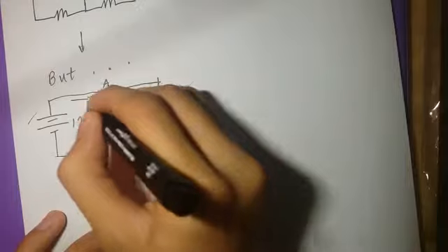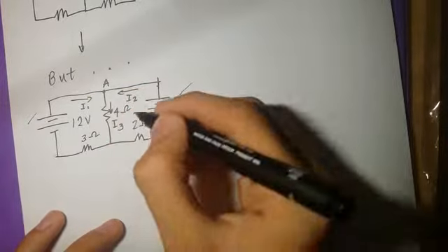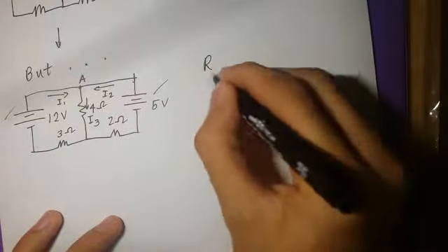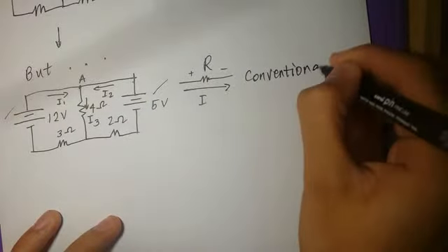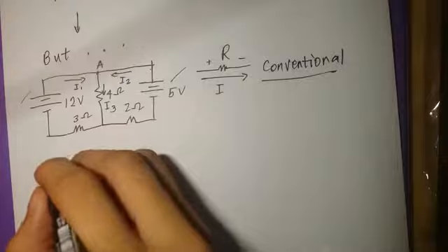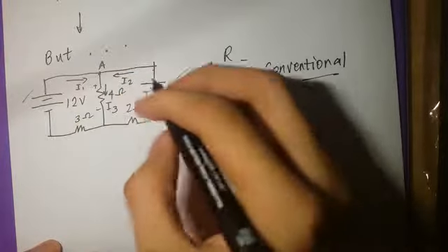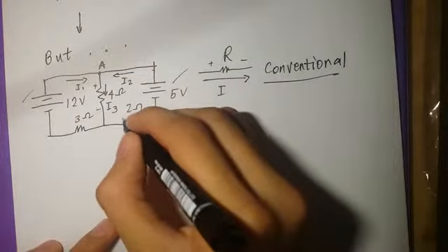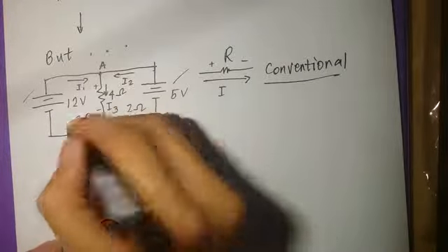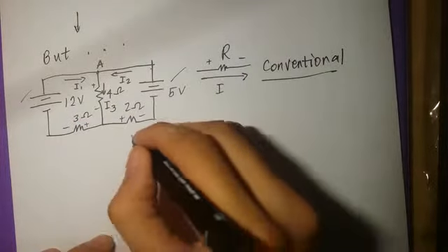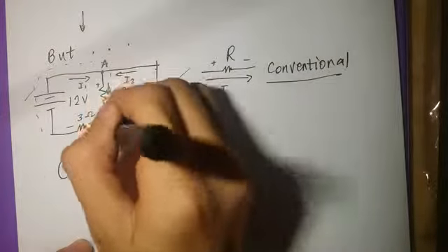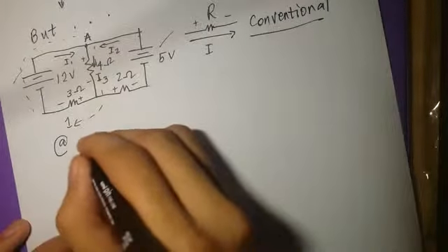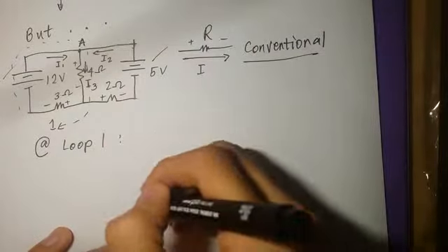And let's represent the 3-wire node as node A. And let's assume the current flow. Now, in a resistor, the conventional flow, I always enters the positive terminal of the resistor. So, since we have now polarities of the resistor, let's represent the left branch as loop 1.